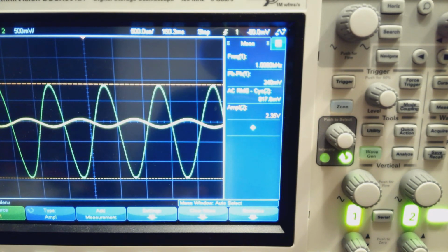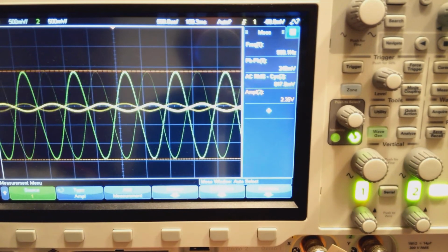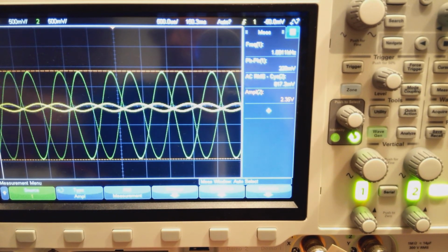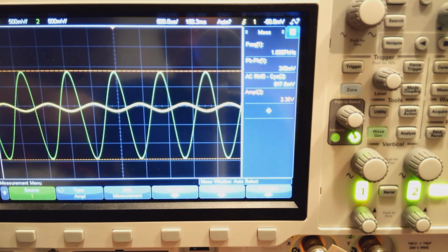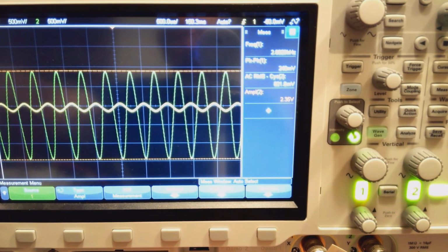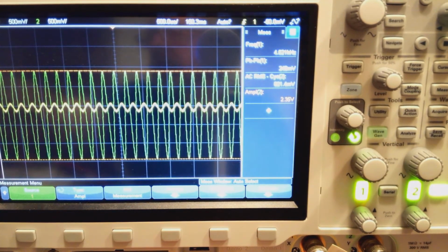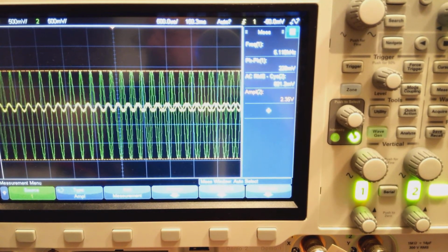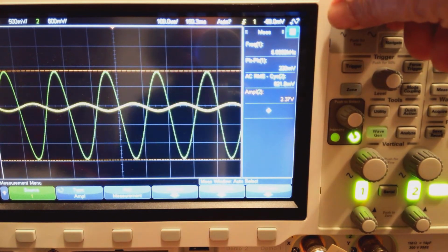The signal generator is putting out a 1 kilohertz signal, as I mentioned before, so let me get this running, and let's show you what happens as I change the frequency. You'll see that there's more cycles, so I can go up in frequency. The gain doesn't change very much at all. Right now I'm up at 5 kilohertz, we'll say. Of course, I could set the oscilloscope and show fewer sine waves.